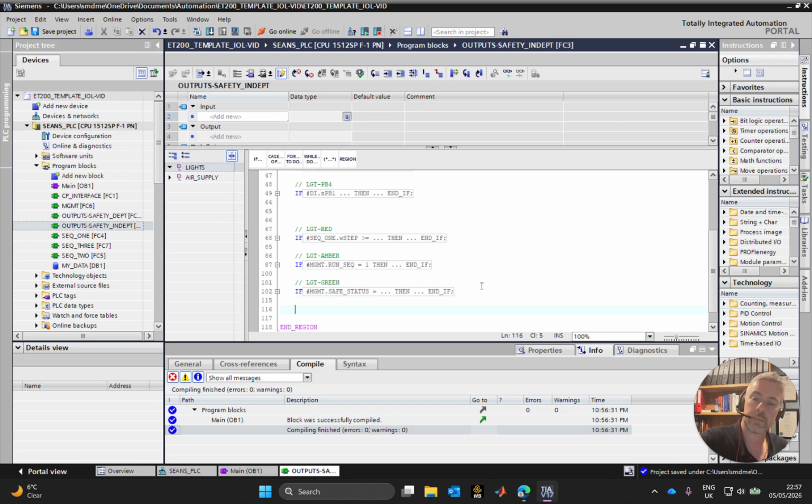But if I was doing Mechatronics from here on out, and I know that I have an IO link light, and I know there's 3 additional points for me to use to turn that on and turn that off and blink it and turn it to different colors, as opposed to using the traffic light, certainly going to use it. So I'm going to bypass this, and in this section here, let's go for a Balluff BNI IOL-800-000-Z036. Let's code that in here.